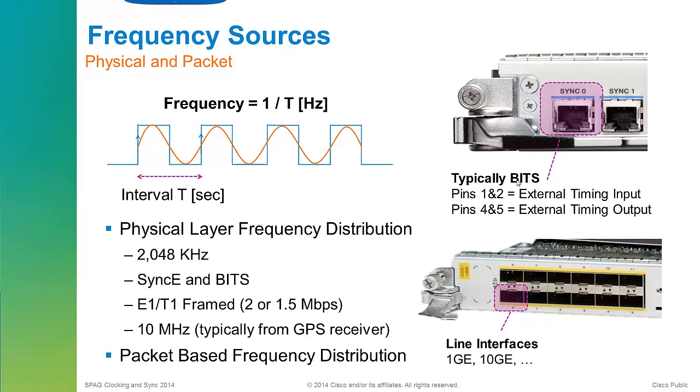Typically, you've probably heard of BITS. BITS is a technology for giving signals for frequency sources to network equipment inside data centers and service provider premises. I use the expression BITS here. I should point out that it's actually a US ANSI term. There is an equivalent term, SSU, in the ITU world, a synchronization supply unit, but basically you'll hear me talk about BITS, and when I mention BITS, I'm talking about an external physical frequency source. It can be either 2 megahertz in the ITU world, or 1.544 in the ANSI world.